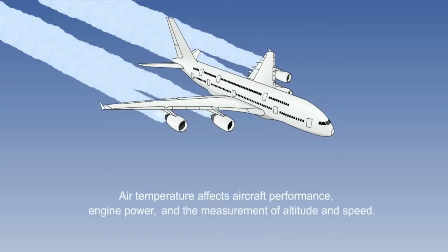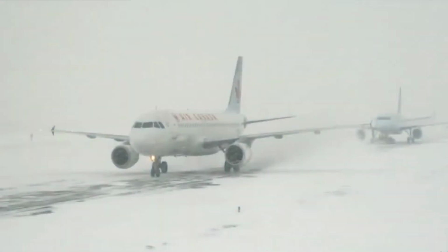Measuring the outside air temperature, however, is not as straightforward as might at first be thought, because the movement of the aircraft through the air will cause the air temperature to rise in the immediate vicinity of the aircraft, as a result of friction, or kinetic heating, and air compression, or adiabatic heating. These terms are fully explained in the next lesson. This temperature will not be representative of the true outside air temperature. It is the true outside air temperature that we need to know.